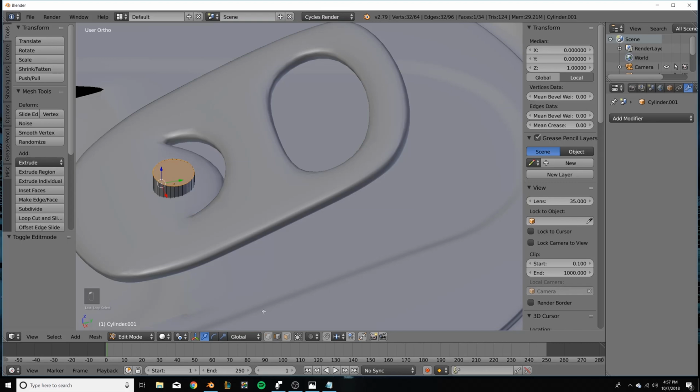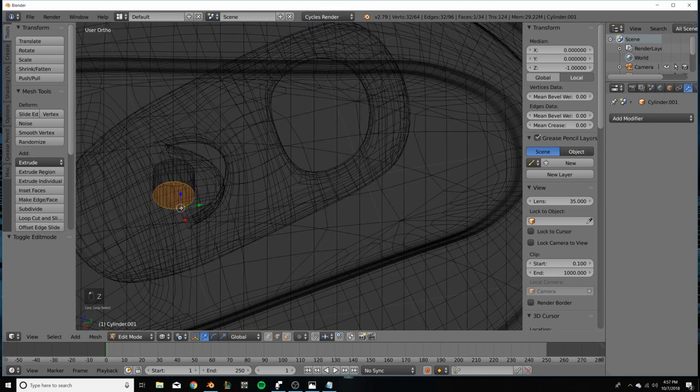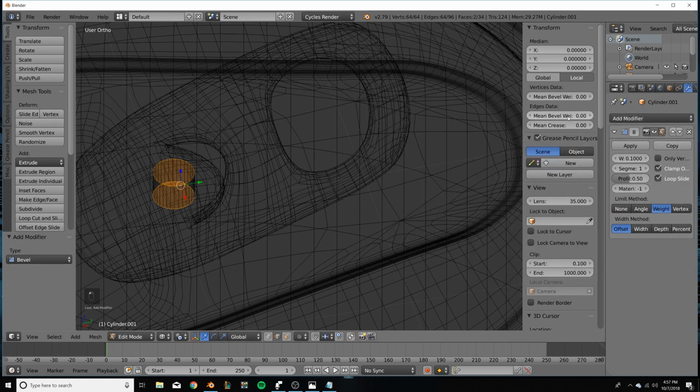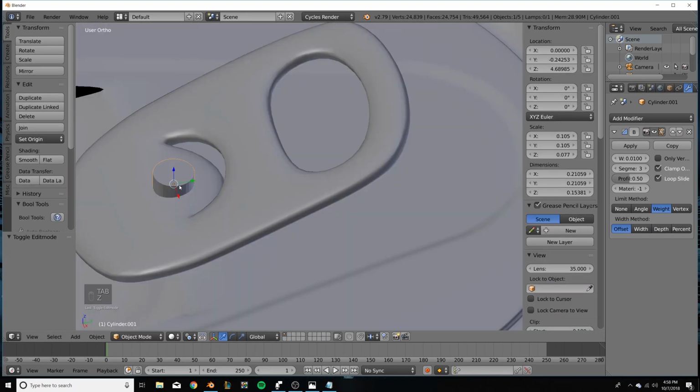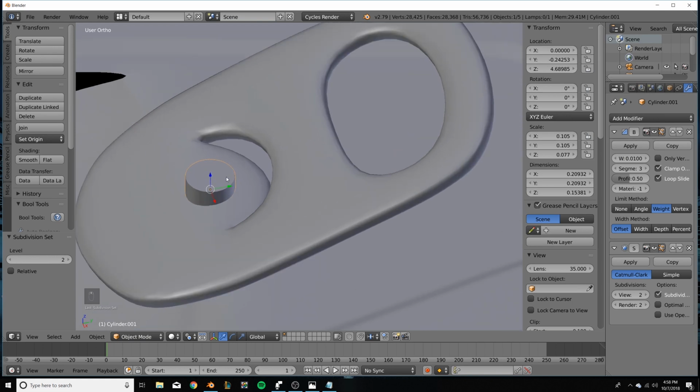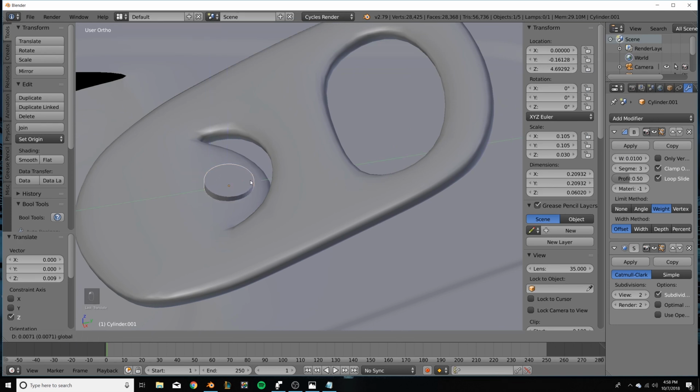Another little thing you can do is have that face selected and this other edge selected, and go to bevel weight, bring this up, put 0.01. That way this will look nice when you hit Control 2 to smooth it out. So we'll just leave it like that. It's just a little small piece that keeps the whole thing where the pivot point is.